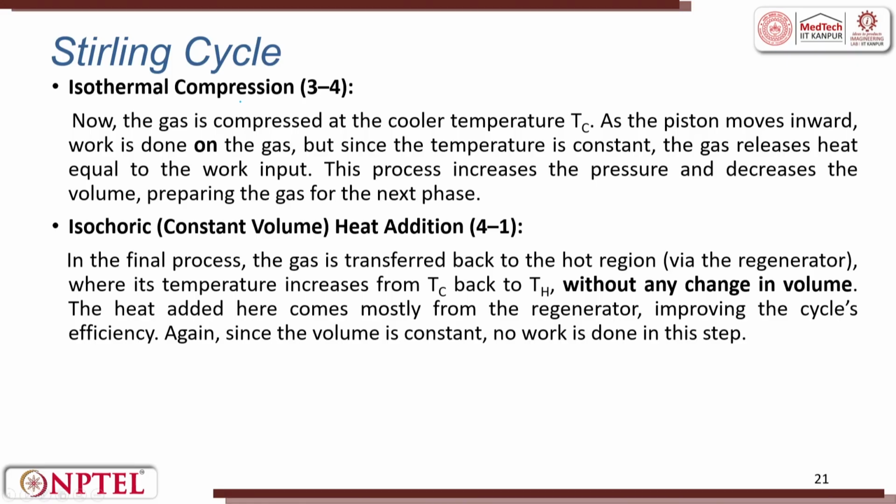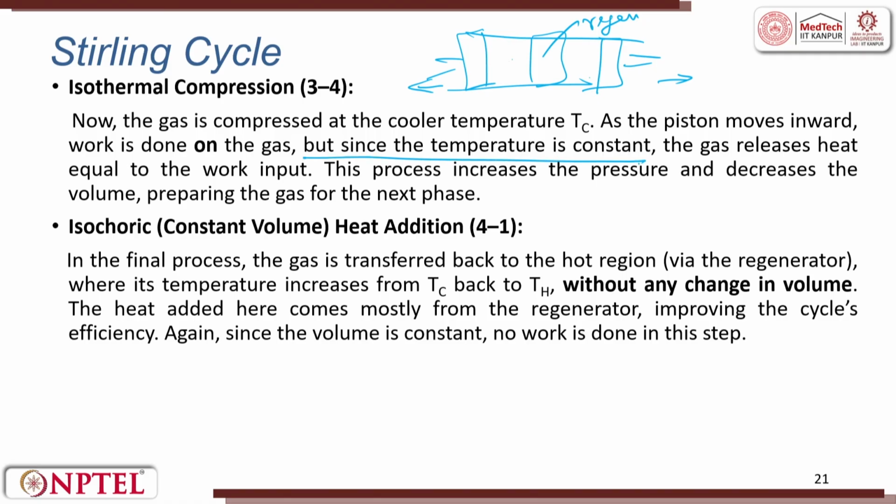Then from the other side you are trying to compress. So, this is regen, this is a piston which is moving, this is also moving. So, from one side to the other side it is going. Now, the gas is compressed at a cooler temperature Tc. As the piston moves inward, work is done on the gas, but the temperature is constant. So, the gas releases heat equal to the work input. The process increases the pressure and decreases the volume, preparing the gas for the next phase.